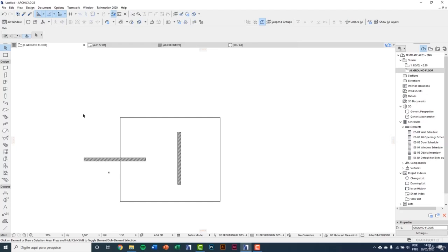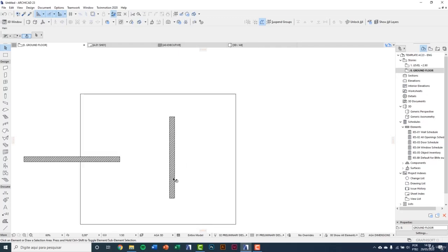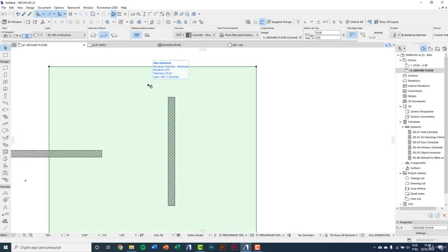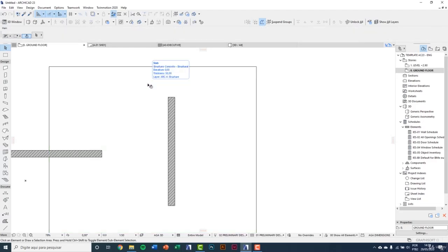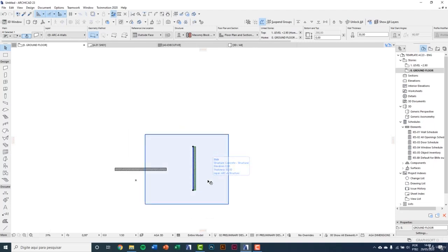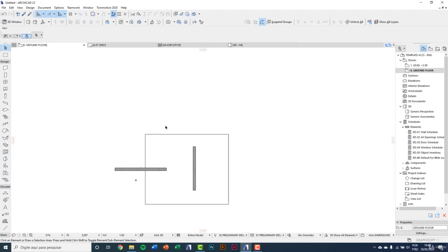For example, I could want to do a rectangle selection in this wall, but making a click, it selects the slab. So I press the space bar to turn off the magnet temporarily, and then I make the rectangle around the wall. And to add selection, you can hold the Shift key pressed, and then you click to add selection, and press Esc to deselect all.